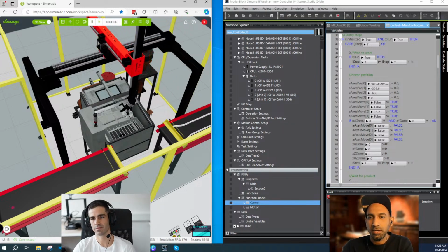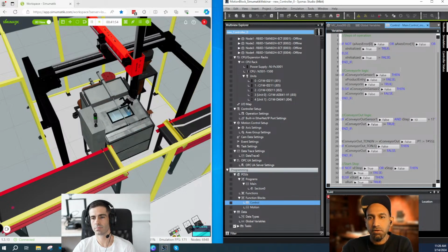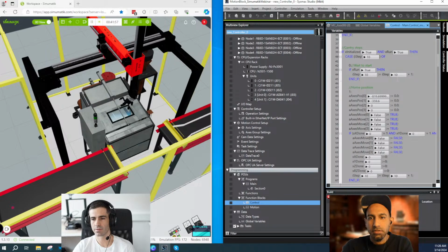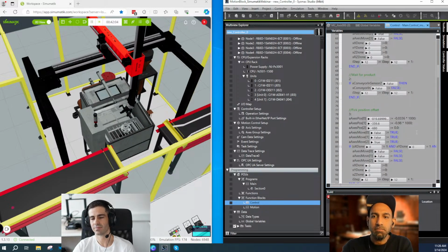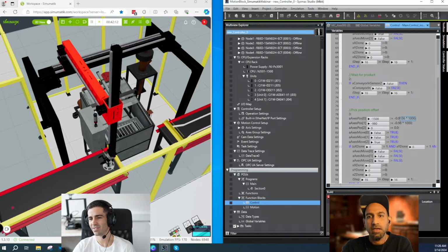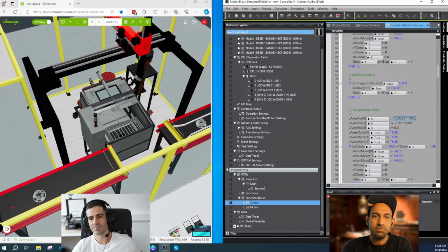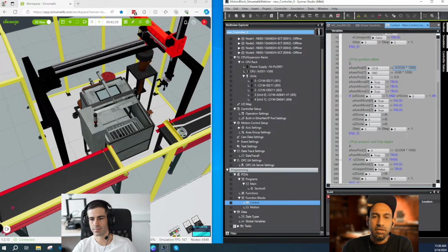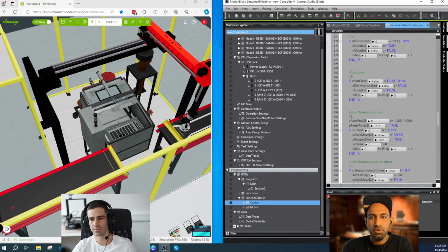If you see in the control part, step number 1, step number 2 and 3, I have mentioned the locations. If you go a little bit down in control, you can see starting with 0, 0, 0. Then if you go to the next step, you will see these are the numbers where I have to mention the location where it has to go for picking and placing. You can notice I have multiplied with 100 because I had the location in meters in Codesys. I just need to add a gain of 1,000 to convert that into millimeters. So that's what is happening. All the recipe data or positions I have mentioned in this control block.